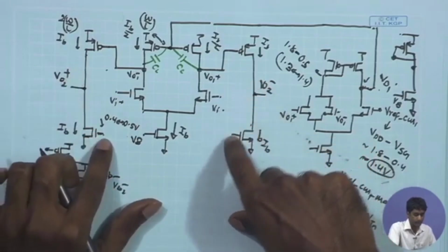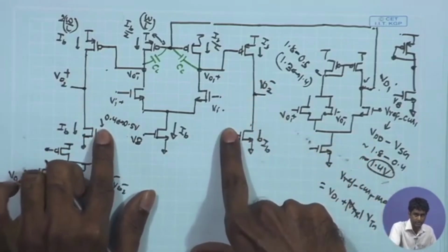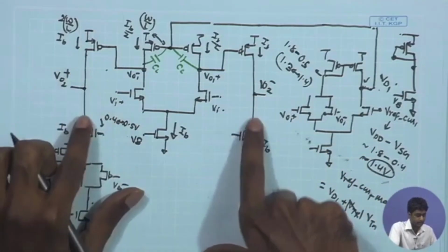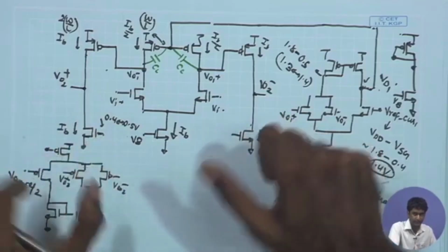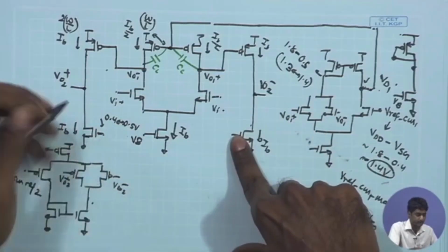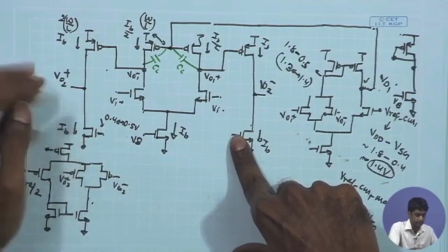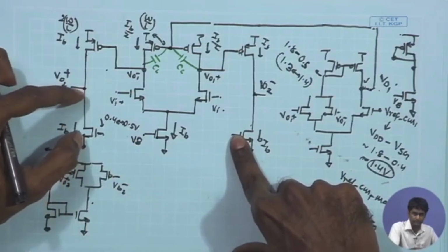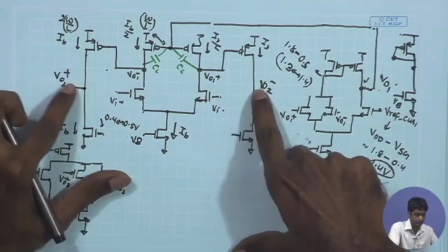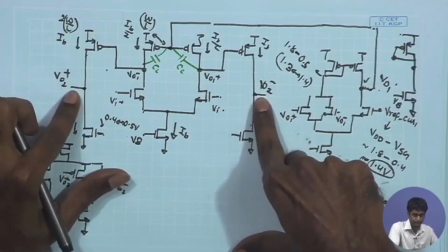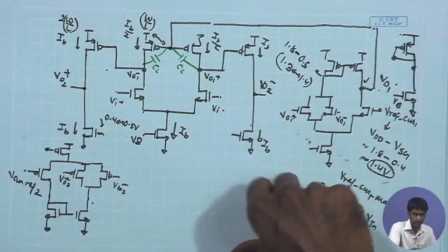The only option is to increase this gate voltage so that the VGS term in the equation becomes larger. As a result, it will be able to support the same current with a smaller drain to source drop. So it will try to bring the DC point over here lower.